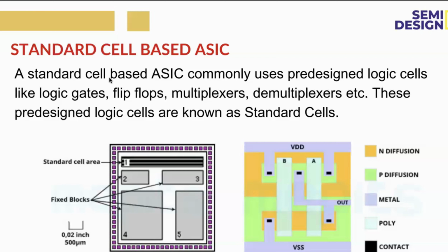Have you understood, everyone? Mostly micrometers. Here the CMOS technology we used was in terms of micrometers, like 1.5 micrometer, 0.6 micrometer, with voltages in the range of 25 volts, 10 volts. So what is the gate count in terms of micrometer CMOS, and the die size?